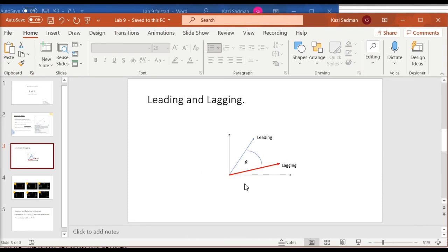So you do that, and we got cos 90 degrees. That means for this x-axis, I could make it over here or over here, right? All you have to do is make an anti-clockwise 90 degree rotation, leading, for the current. So this is going to be the voltage and this is going to be the current, where for the capacitor the current is leading by 90 degrees. It's pretty simple, okay? So this is what you have to do for the rest of the circuits, so just start working on it, and that would be all. Good luck.